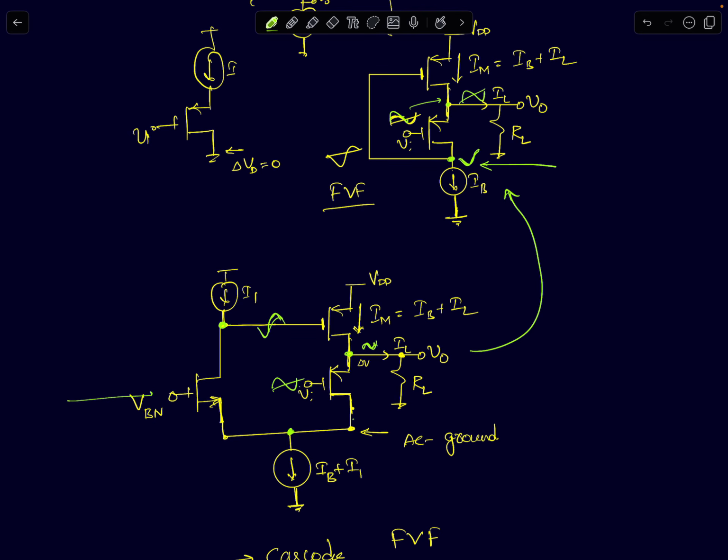The only difference is now the drain voltage, because I'm forcing the current through this device to be constant, the VGS of this device is constant. See, again, when I say it's constant, I'm assuming it's nearly constant. Okay, it's nearly constant, then this node voltage will be VBN minus VGS, which will also be constant. So I have achieved a behavior very close to a common drain amplifier, with the drain node voltage remaining calm here. It's not changing much.